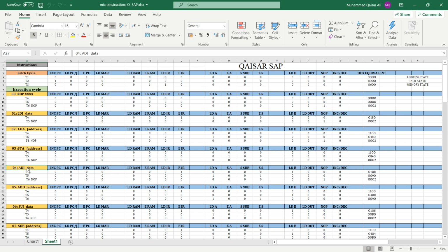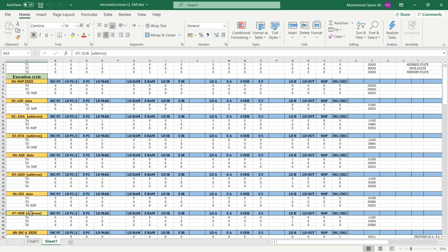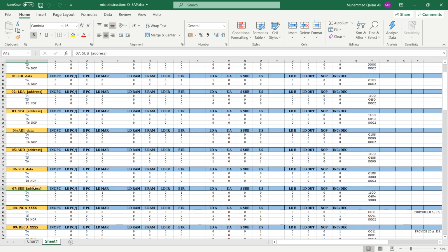Through this instruction, you just directly feed that data to the adder or subtractor for addition. Similarly, we have instructions for subtract, one direct and one indirect, through RAM. The data should be present at some address, then you load that data to the B register. The first operand is already present in the A register, and you do the subtract operation. Over here the case is different. Here the data will be directly fed to the B register, and the first operand will be in the A register, so subtraction will be performed in this way.